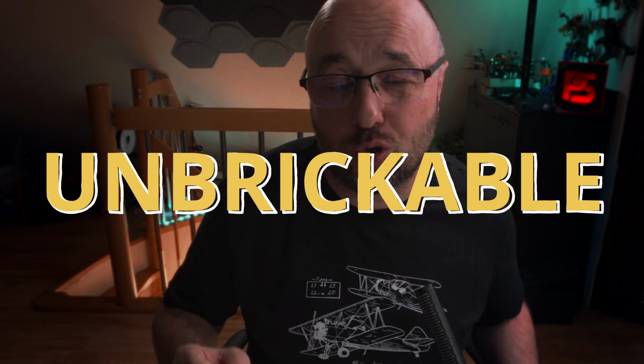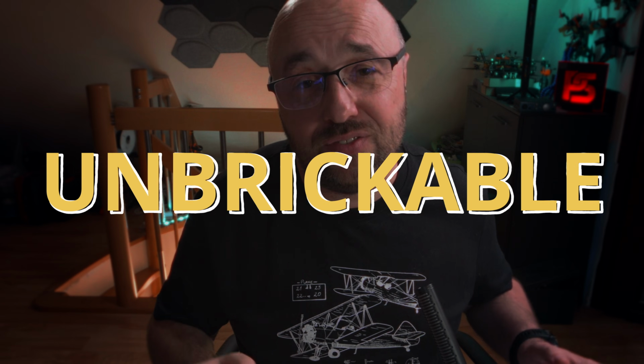And no, you cannot brick the flight controller, at least if this is an STM32 flight controller. The bootloader on the STM32 flight controller is located in the read-only memory. You cannot just override it. It will always be there, and that means that you can always flash.